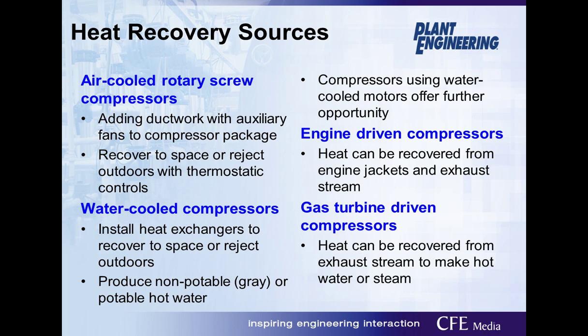So some of the areas you can look at. For air cooled rotary screws, looking at ducts, recovering space heat when outdoor temperatures are good. I'll preface that this works where I'm at in Michigan, but if I go with one of my other instructors who's down in Phoenix, it doesn't work very well. But if you have something that can offset HVAC requirements for heating, that's a perfect example. Water-cooled compressors, you can use heat exchangers to recover it and either put it in for heating or use it for sources that may be used in the production process.